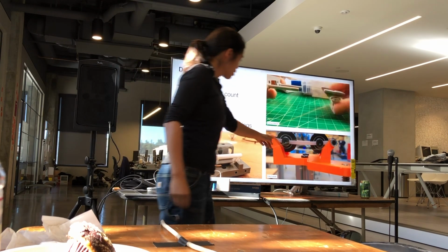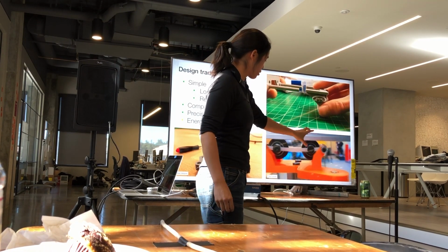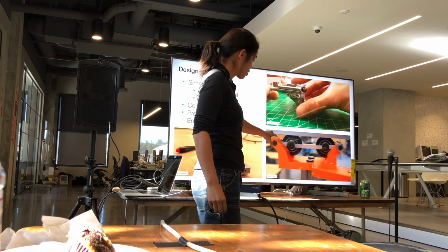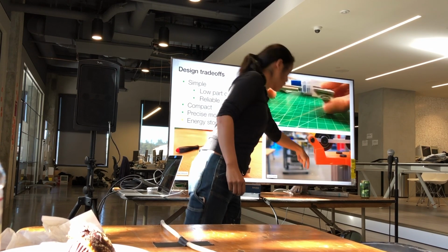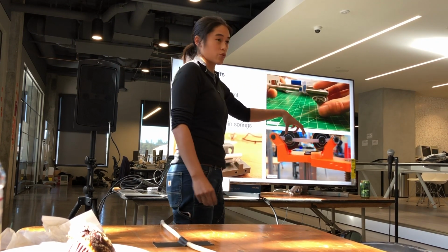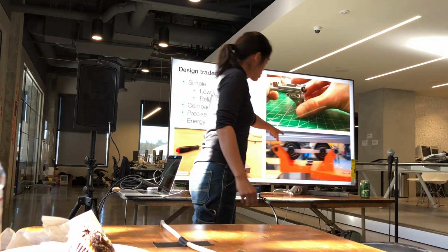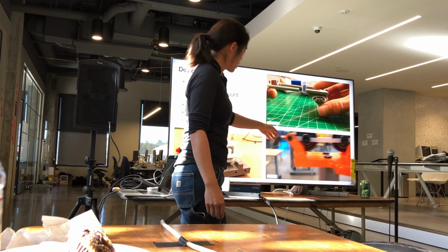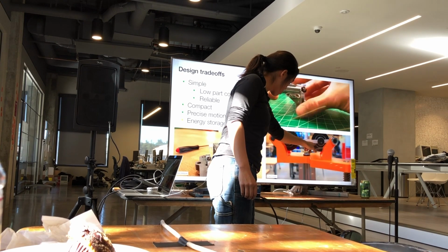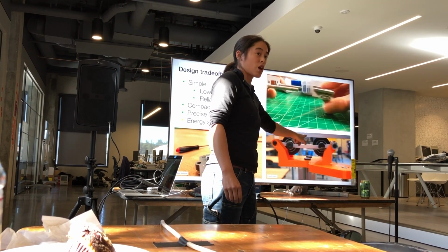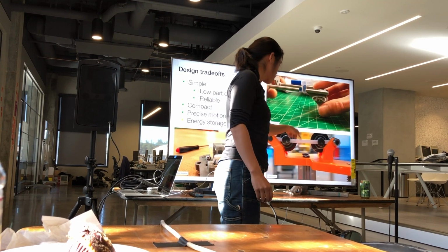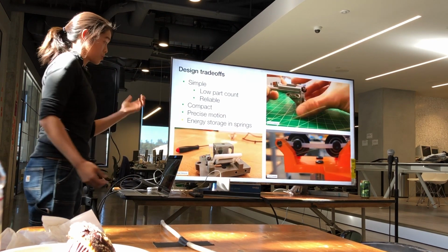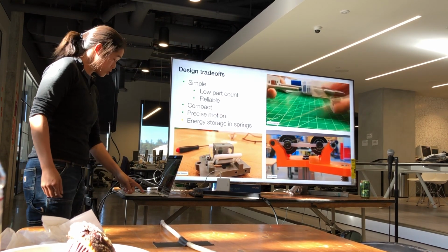This is an example where this is part of a linear rail structure. The bottom part of this beam, not shown, has rigid rollers, and the top beam here might not be perfectly parallel with the one before. It's hard to see, but this beam bends very slightly as it travels, and so you're relying on the compliance there to make sure that the mechanism works well.